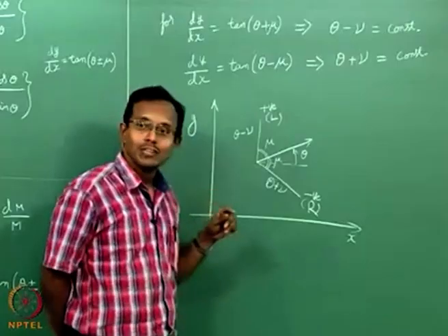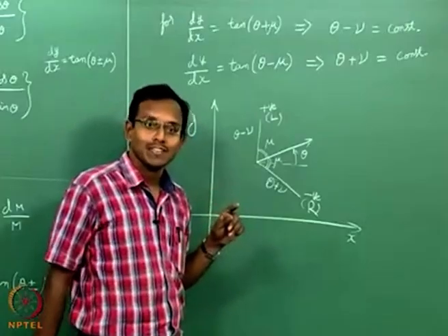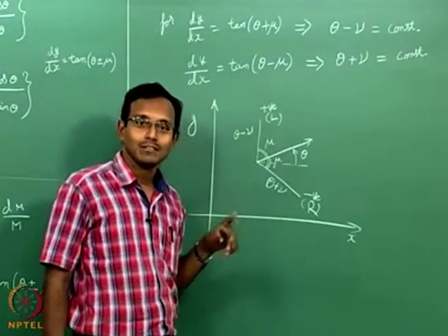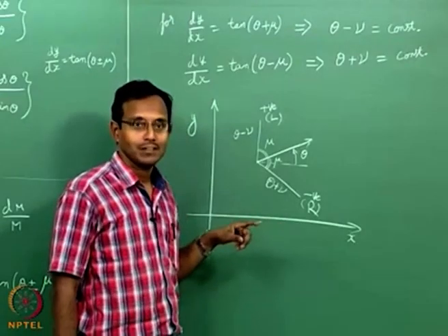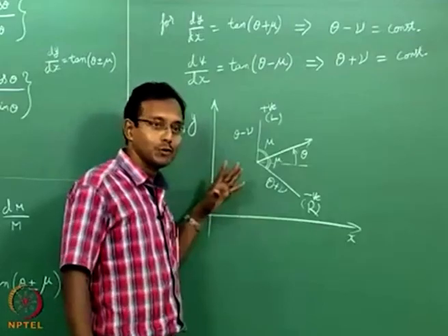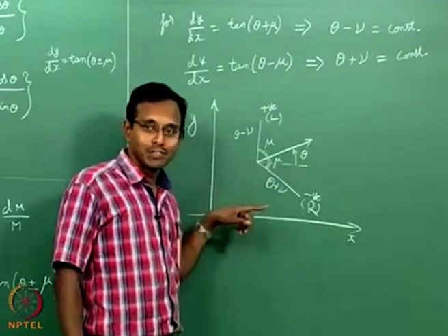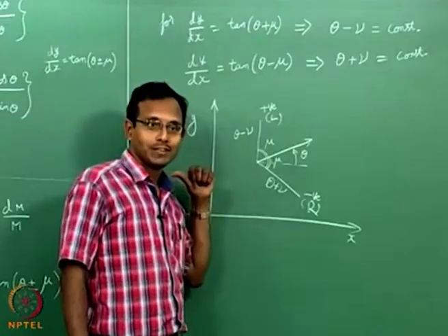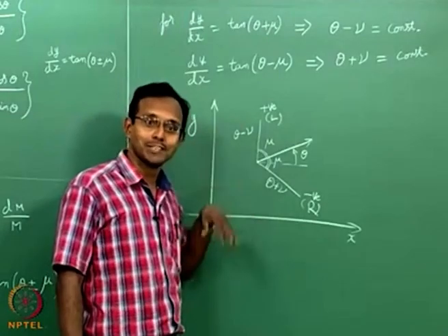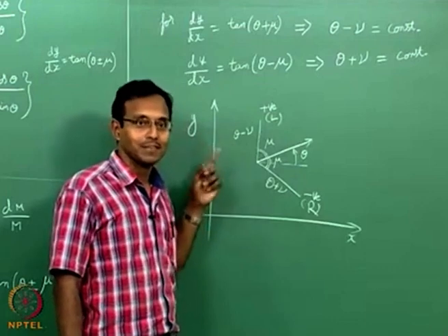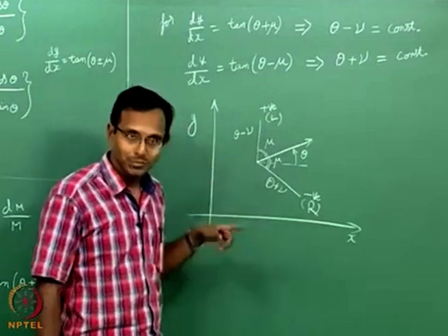Now we have to think about one more thing. Supersonic flow, we said, depends only on upstream conditions and not on downstream conditions, right? If I think about one particular stream tube, the flow happening downstream depends on the upstream and does not depend on downstream. It may depend on the side of the stream. Okay? It does not depend on downstream conditions.